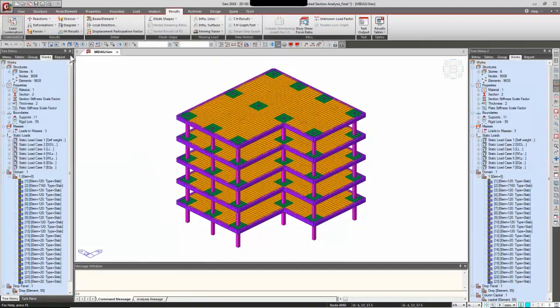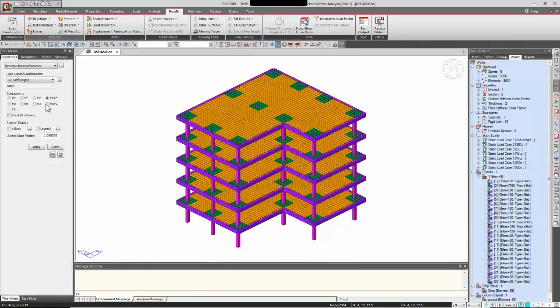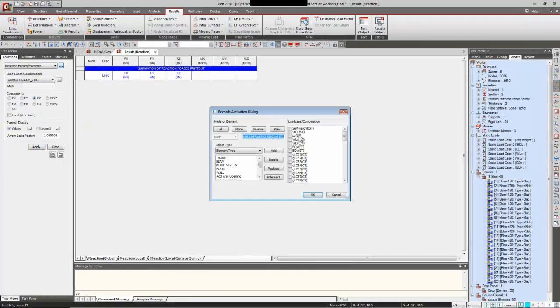And we will go ahead now to checking the reactions. We can get the reaction forces and moments on our workspace. We can simply select our maximum strength envelope and let's see the vertical reaction. We'll see the values. These are the values, and the red one shows that the maximum reaction has been obtained at this location. We can click over here on this three-dotted box for every result and get our results in the form of tables.